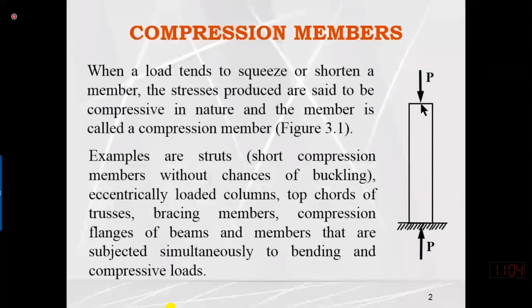When we apply tensile forces, if the member is initially bent, it will be straightened and then start taking the load. It will only fail when the applied stress is more than the yielding stress at gross area or the rupture stress at net area. So the failure might be rupture failure or yield failure.